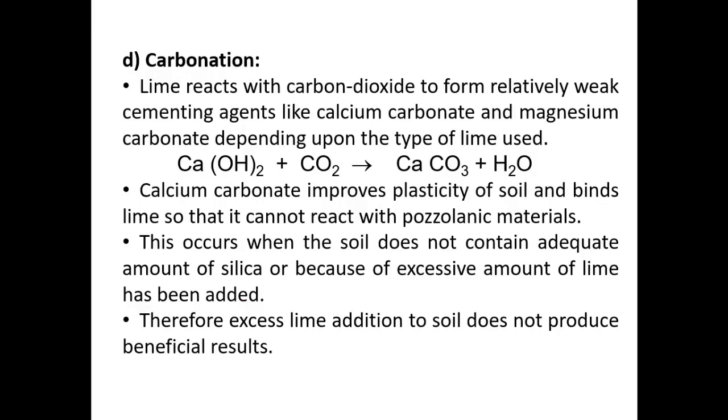Next reaction is carbonation. It is an undesirable reaction that occurs when the calcium ions react with carbon dioxide present in the air or in the soil, and calcium carbonate is formed. The calcium carbonate is a plastic material, a weak cementing agent, which increases plasticity of soil and retards the pozzolanic reactions by binding the lime.